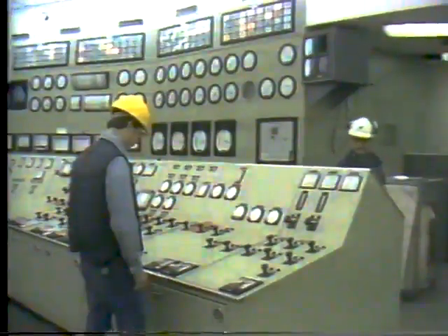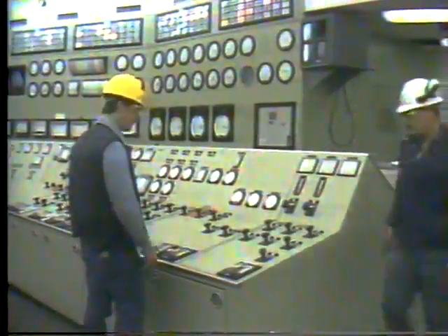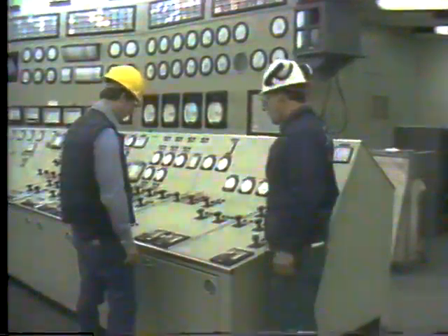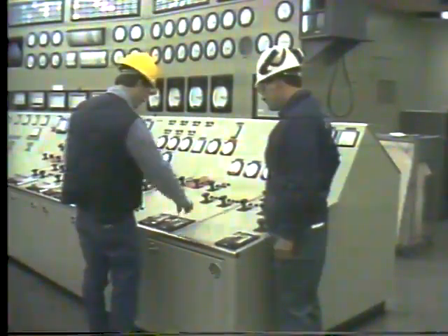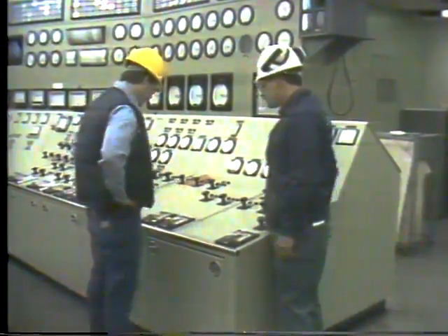Now, when you're asked to tune a system, you don't just walk up to the controller and start making adjustments. The first thing you do is to learn all you can about the system. There are several different sources of information that you'll find useful. One useful information source is other people who know the system. These people are control room operators and many of the experienced instrument technicians that you work with.